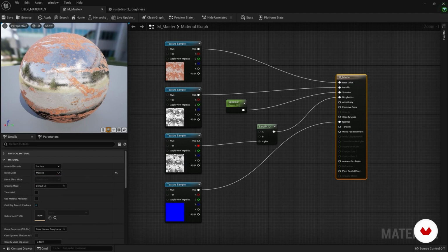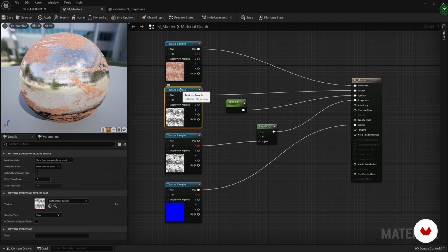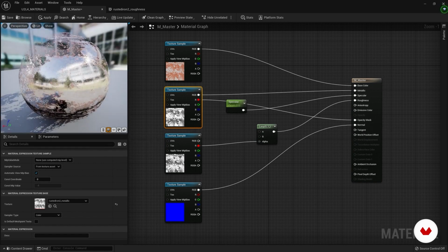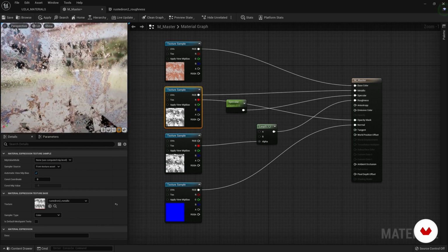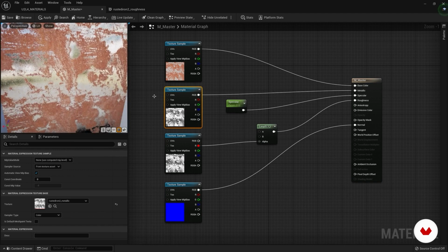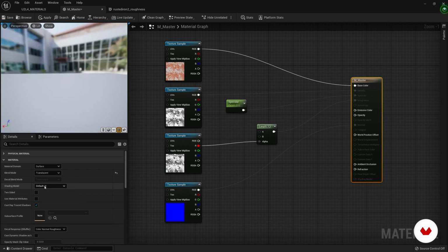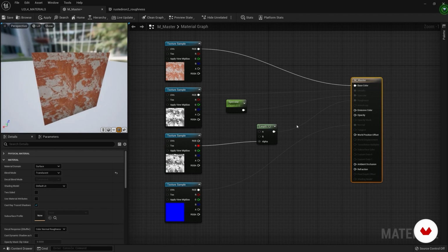Masked is a kind of material, you see, opacity mask node is turned on. Basically, it defines the opacity of a material. It works a bit like metal's roughness and map, black and white. Where it is black it is opaque, where it is white it is transparent. In fact, if we use the metal map on the opacity map, do you see that it has become transparent? But it does it in a clear way, it does not allow for nuances.